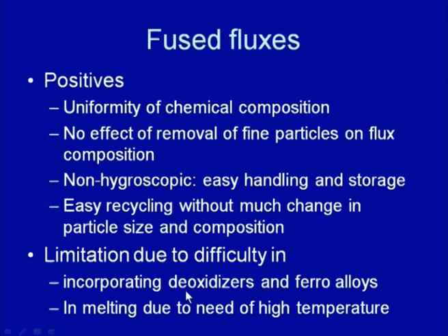But there are certain limitations associated with the fused fluxes and these are related with the difficulties in incorporating deoxidizers and some ferroalloys in these fluxes. And the second is the difficulty in melting of the constituents which are to be used for making these fluxes, and this requires very high temperature to bring them to the molten state. So, high temperature requirement for melting is another difficulty associated with the fused fluxes.